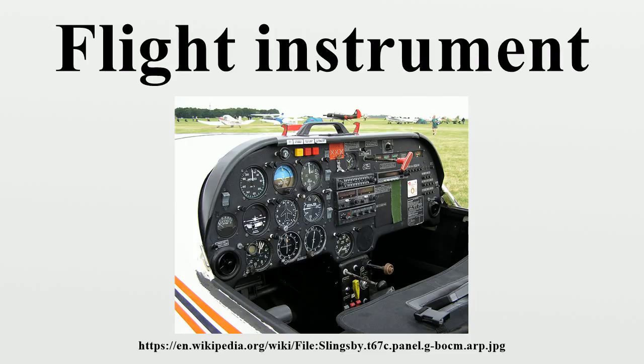This basic 6-set, also known as a 6-pack, was also adopted by commercial aviation. After the Second World War, the arrangement was changed to airspeed, artificial horizon, altimeter, turn and bank indicator, heading indicator, vertical speed. Further development of the old basic 6 instruments: the turn and bank indicator is now obsolete.